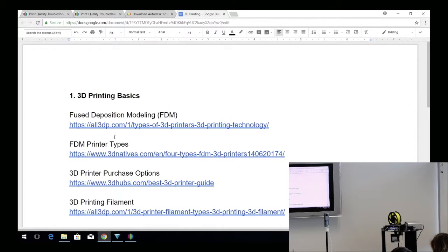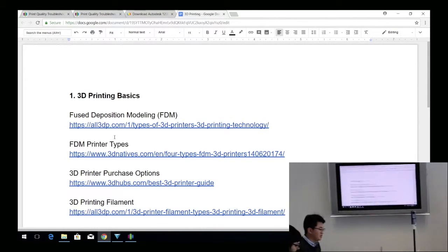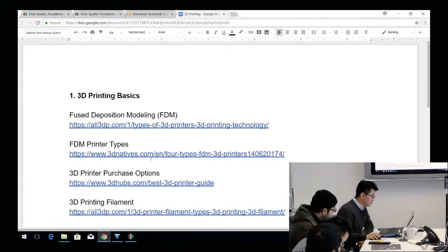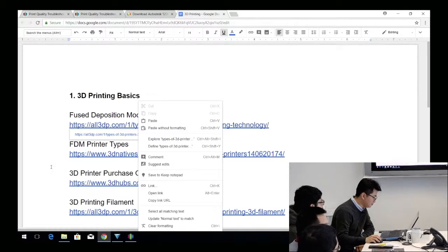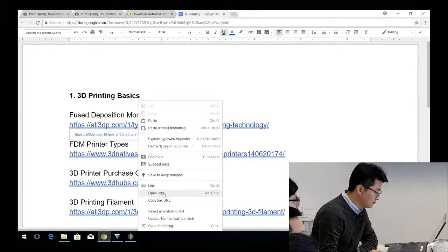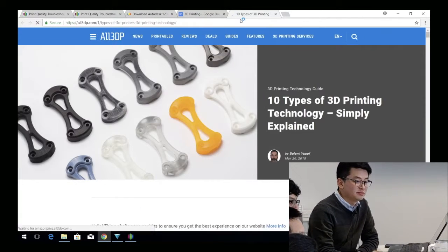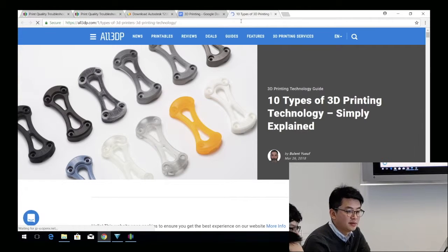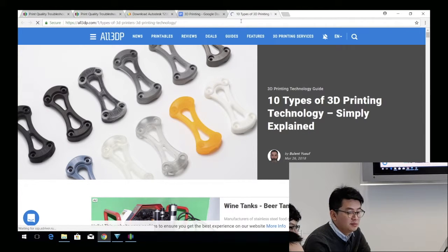There are tons of other printers. Actually, what I really want to mention is this one. I think it's a design flaw with the MakerBot, because the gear mechanism is so close to the extrusion nozzle. If it's having problems, the plastic's already melted and the teeth just start wearing at it and then it becomes stuck.